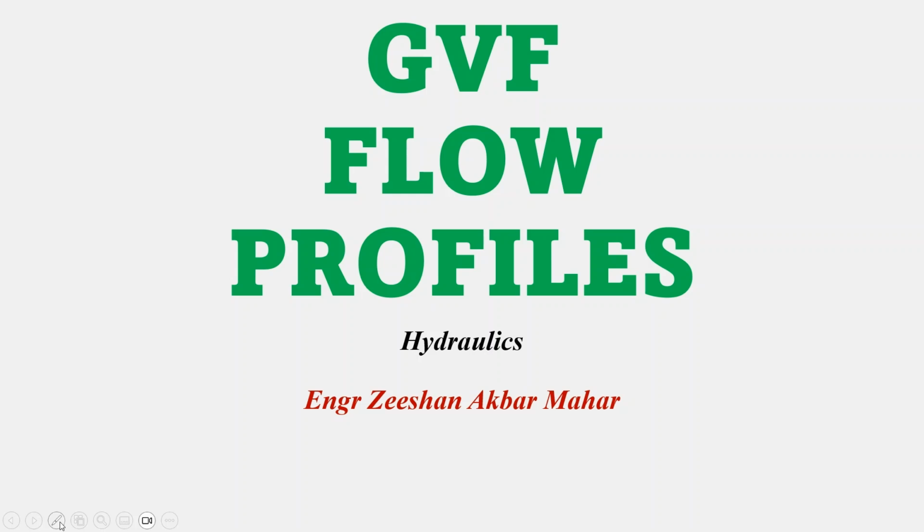In this video, we'll discuss the possible profiles for gradually varied flow, that is, how many types of profiles can be observed for GVF in hydraulics engineering or in open channels. Basically, we have five types of slopes for the case of gradually varied flow. It means our channel can have five types of arrangement depending upon the slope for GVF.